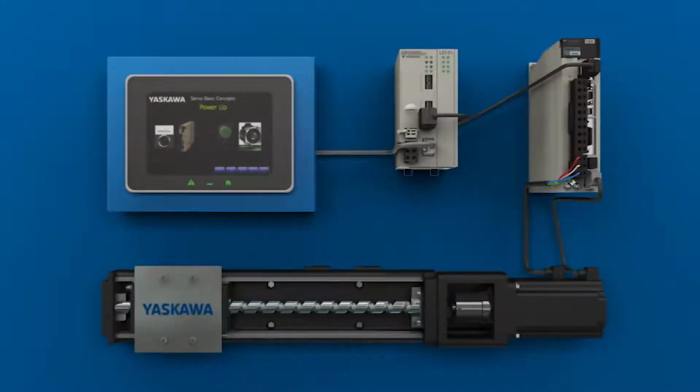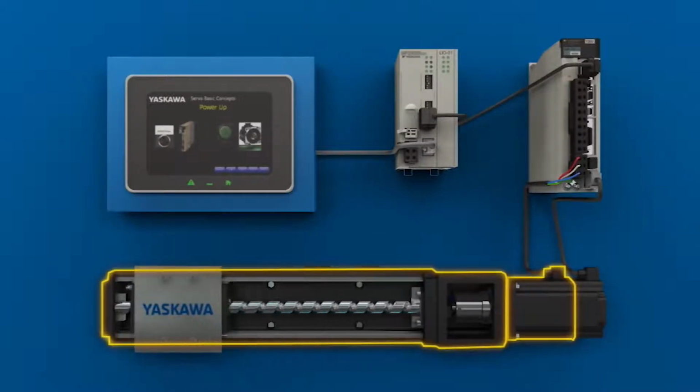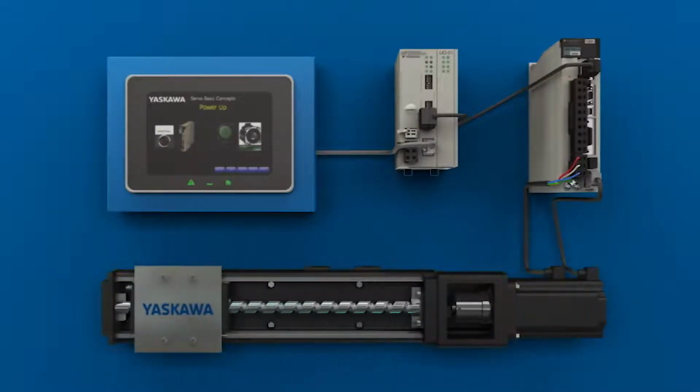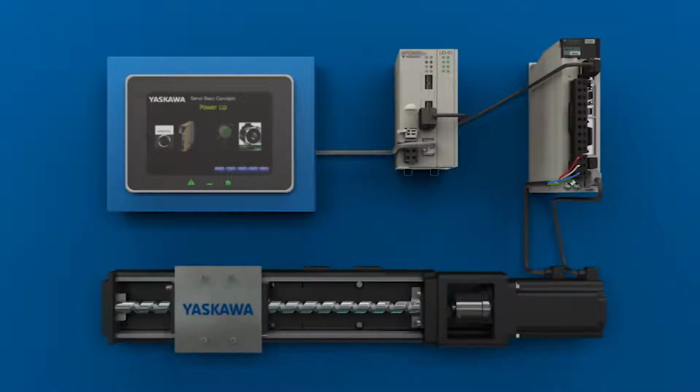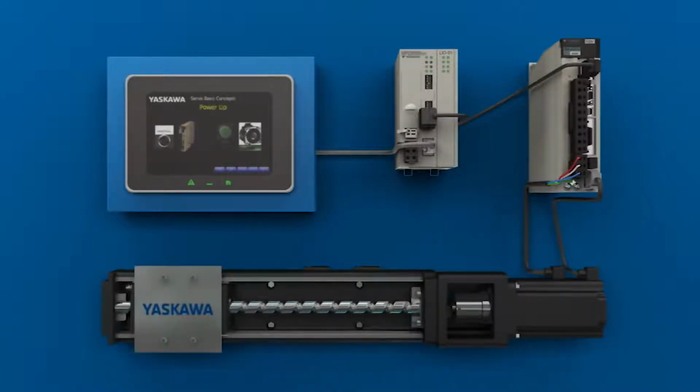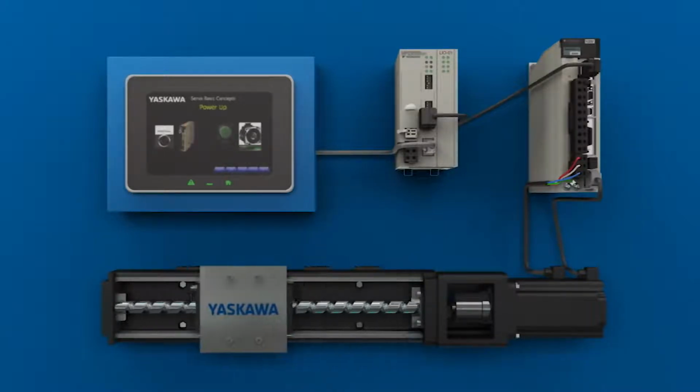On the other end of the process, the servo motor is connected to a mechanical system that it moves, the servo mechanism. This is a common example, a simple linear actuator that translates the servo motor's rotary motion into linear motion, in this example using a screw. This is only a simple example. The mechanisms used in industry can be complex and diverse, depending on the job that needs to be done and the imagination and expertise of the machine builder.